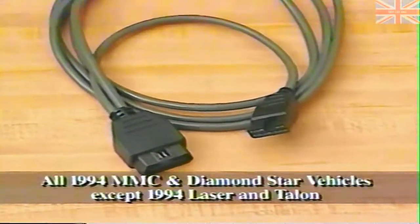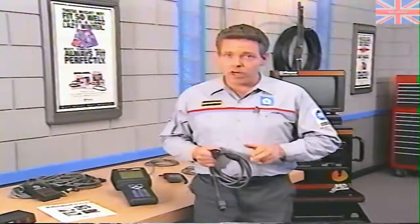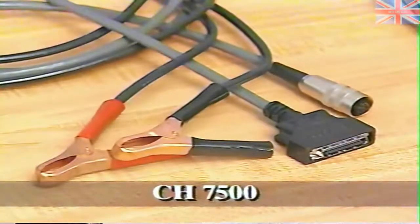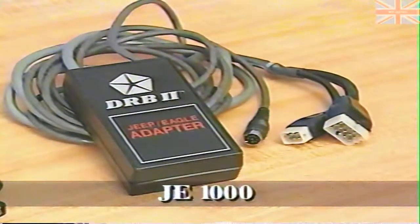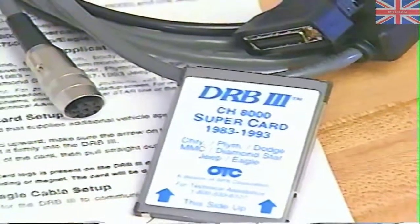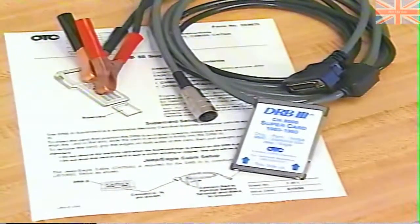In addition, there is one cable listed under Cable Usage Help that was not included in your DRB3 kit. This cable, CH7500, is required for the DRB3 to communicate with certain Jeep and Eagle vehicles using the adapter JE1000. This cable is available with SuperCard CH8000 in kit CH8001 or separately through OTC. We'll discuss the SuperCard a little later in the program.